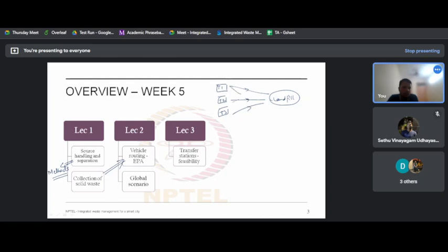So it is better for them to collect their wastes at a depot. That is called the transfer station. And from there, maybe a big truck T4 can take it to the landfill. It can help minimize the cost, but we need to check if this is feasible. If the distance is very short, it is better for these trucks to directly take the waste there. So this is usually done when the landfill is too far.